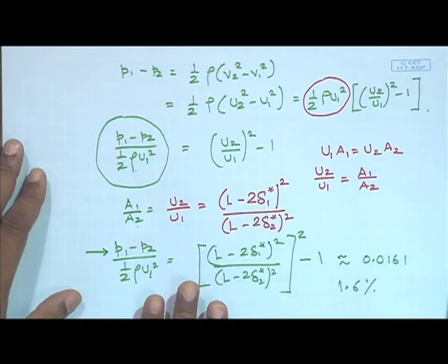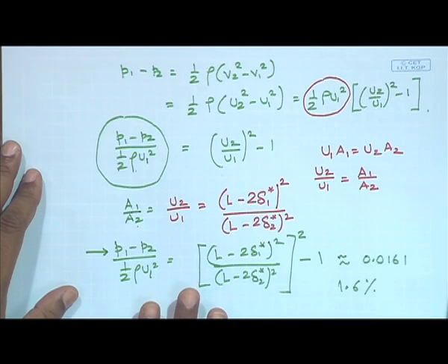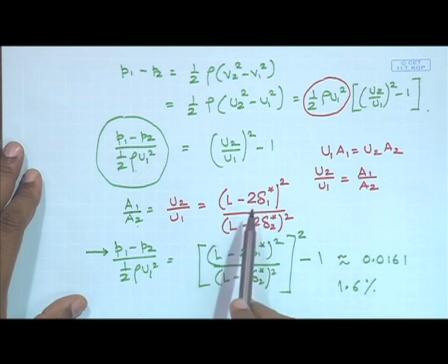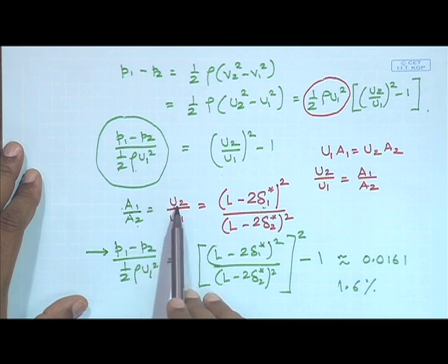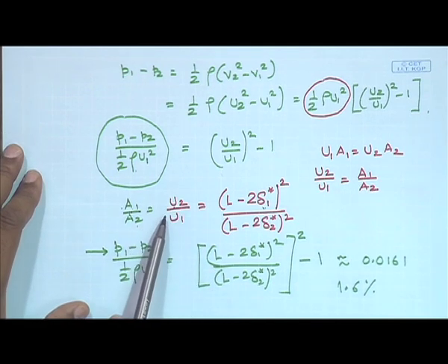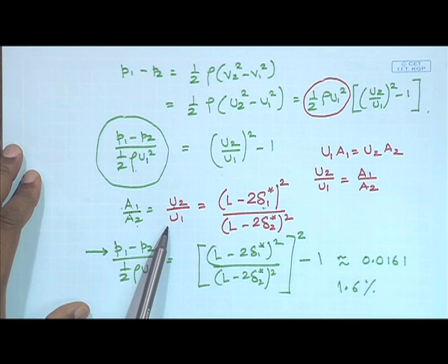This is a nice example where you would get an idea of what is the use of the displacement thickness in order to obtain what would be the free stream velocity, what would be the new area and the free stream velocity when we replace the viscous flow, that is flow with the boundary layer, with an inviscid flow where at all points the fluid is moving with the same velocity.